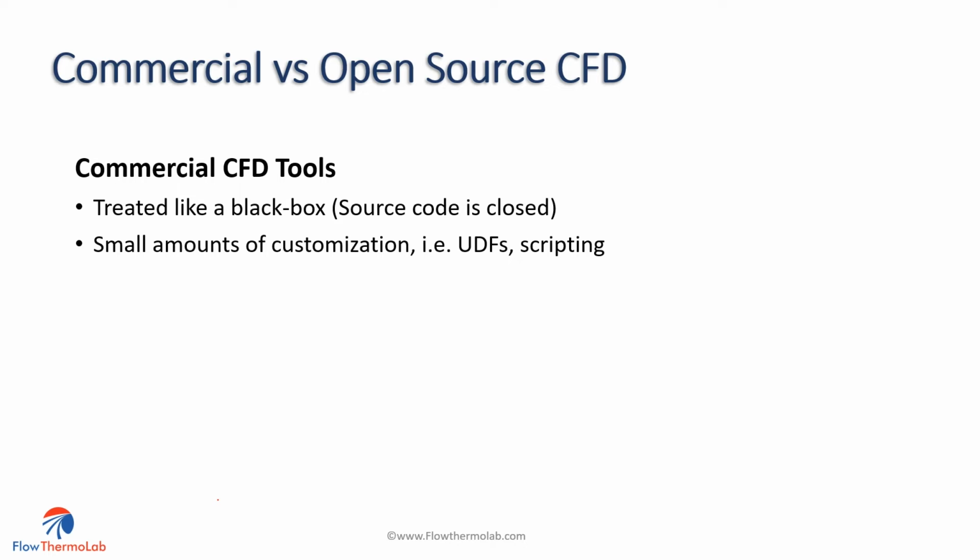You can have small amounts of customization, i.e. through UDFs in Fluent, JavaScripting in StarCCM, but that's quite limited. You don't really have much control over the code.